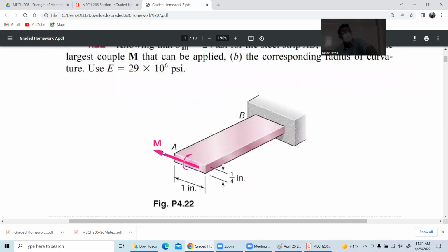Please focus here. Force is not applied towards the left. Force is applied from the bottom. The beam is actually bending like this. That's why the moment is in that direction. So look at this arrow. This one. Do you see this? This means that someone has put the force from the bottom and the whole thing is curling like that.